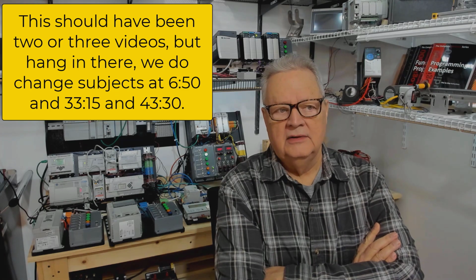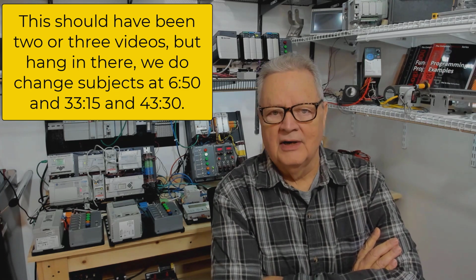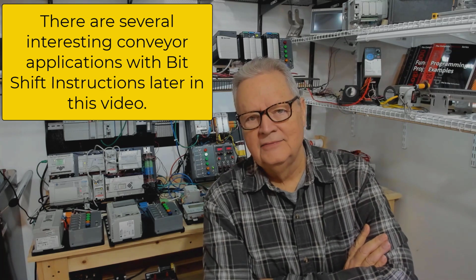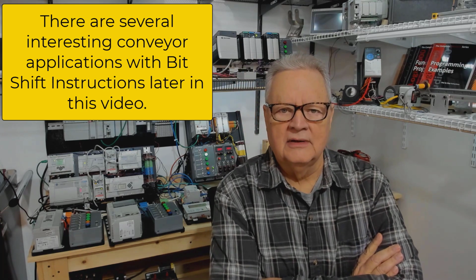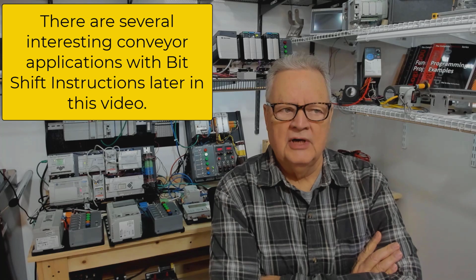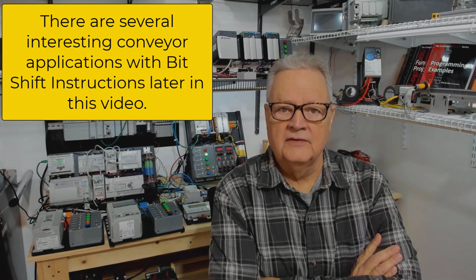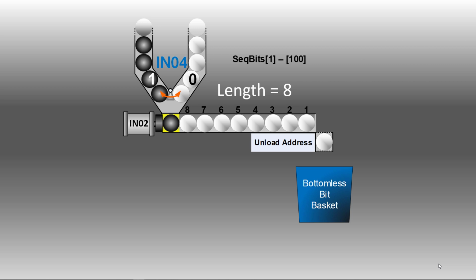With bit shift right, instead of loading the bit address at the least significant bit, bit 0, you load it at the end of the length and then it goes back to the right towards bit 0 and unloads at bit 0. So it's a little bit more complex in how you look at it. So let's jump in and do the bit shift right. We're not going to labor with this diagram like we did for the bit shift left. And you notice what's changed is we have our push cylinder over on the left end instead of the right end. So when it extends, it pushes the ping pong balls to the right instead of the left.